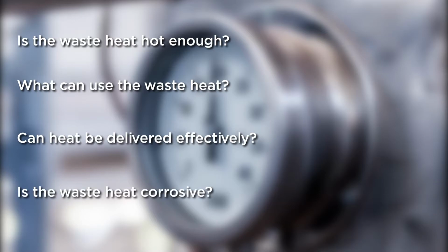Is the waste heat overly corrosive? Some processes that expel harsh chemicals can break down carbon steel quickly. More expensive materials like stainless steel or aluminum will be needed for these applications.